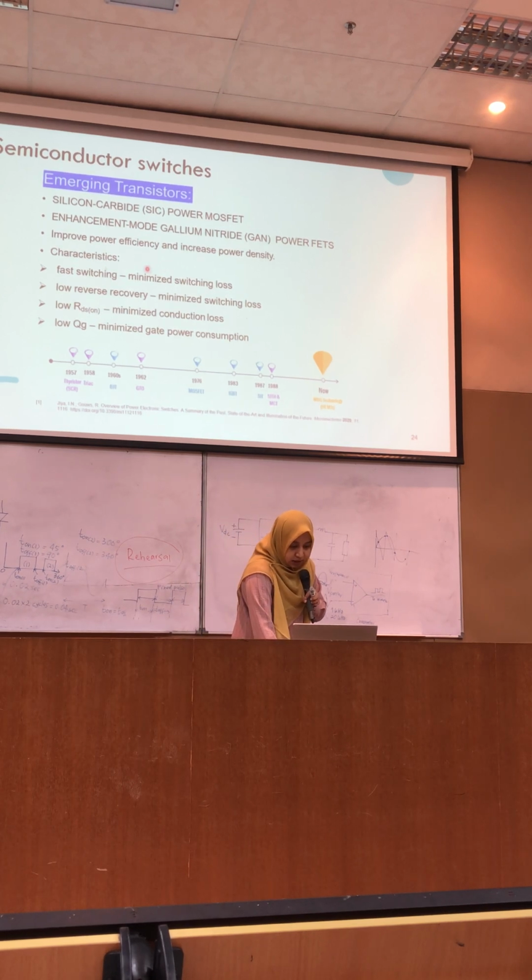Okay, the characteristics of the emerging transistors, which are silicon carbide and gallium nitride. The advantages are very fast switching, low reverse recovery, low RDS on, and low gate power consumption.